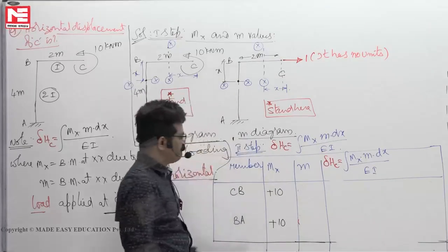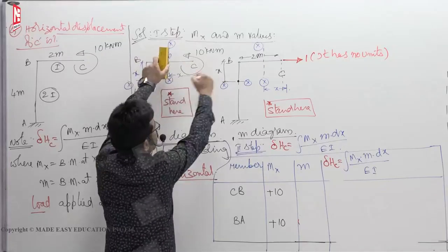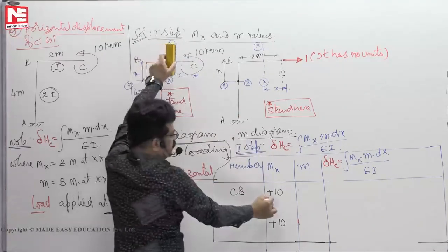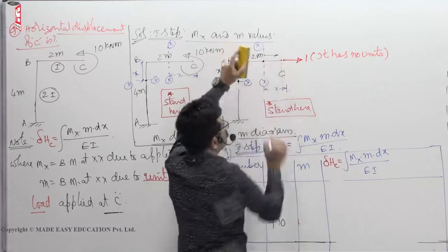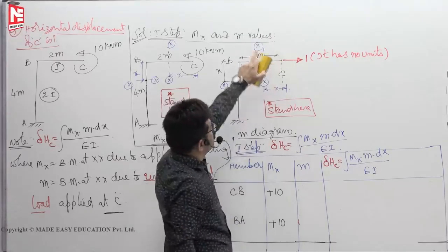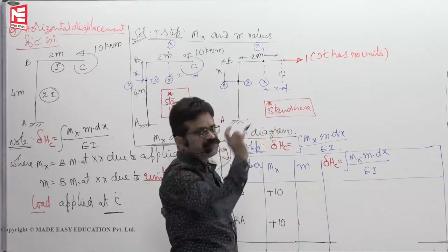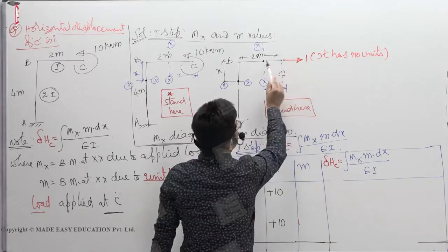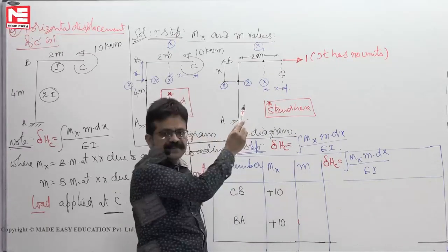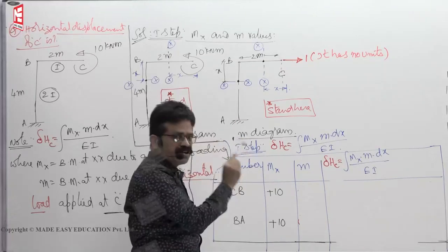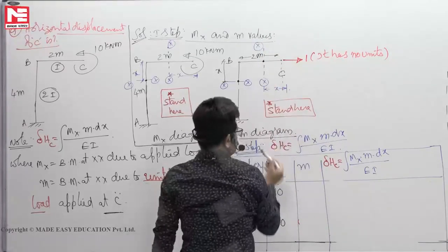Now coming to this problem, this is the table. Stand here, look at this one. Section right side anti-clockwise, plus 10, already written. Coming to this one, due to this horizontal load, what is the bending moment at the dot? Section XX is cutting the beam at the dot. So stand on the dot, look at the force. Travel from tail to the head towards the point. You will find that this force is passing through the point itself. So the perpendicular distance between the dot and the line of action of the force is 0 because it is resting on that. So 1 into 0.